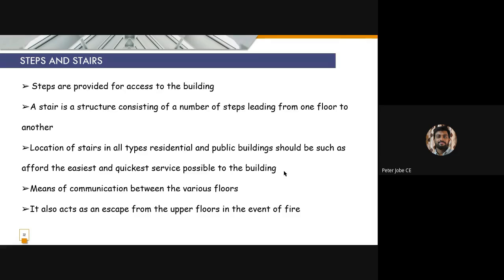While if it's a private building or a residential building, we can have small adjustments in that level, because as the height of each step reduces, the number of steps will increase, and that can lead to more cost. That's why in private properties, we'll keep the height of the steps at maximum. It might be around 22 centimeter height of each step, while for public buildings where different age groups will try to access the steps or stairs, the height of each step will be kept around 15 centimeter.